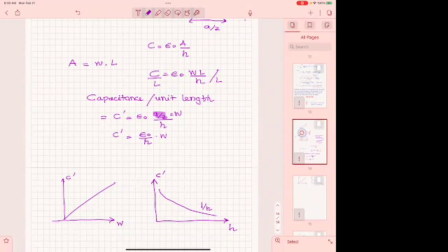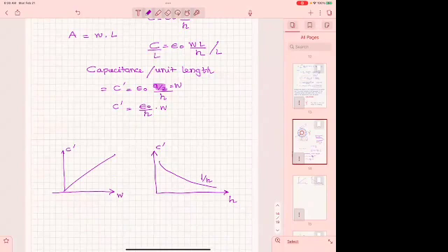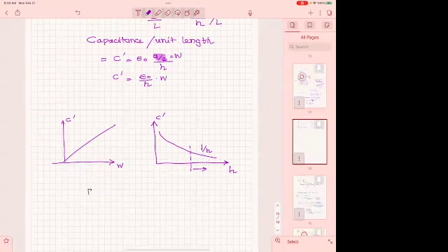these capacitances will be down here. The H is going to be high. The distance with the other grounds will be high. So your capacitance is going to be probably down here, if not in this range, which means all of your parasitic capacitances will be small. That is important to remember. So your parasitic capacitances will be very small. Why is that important to know?